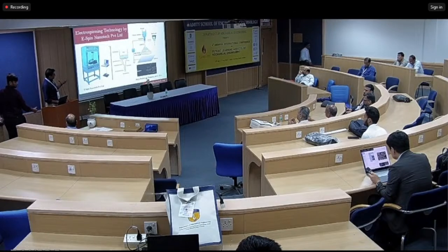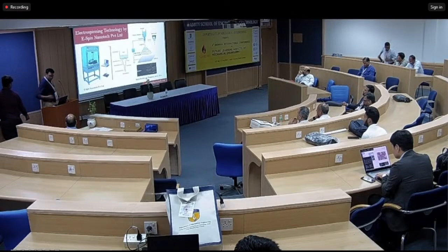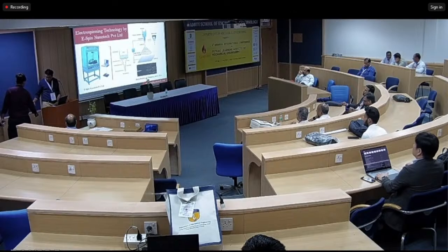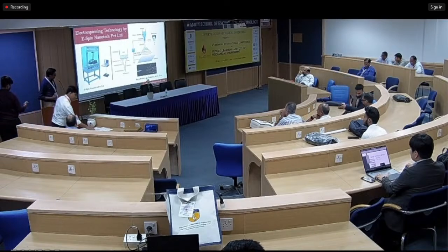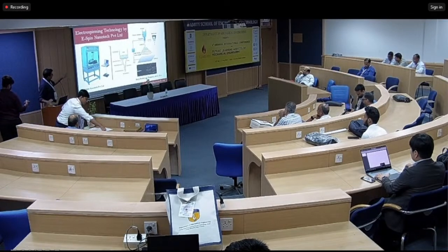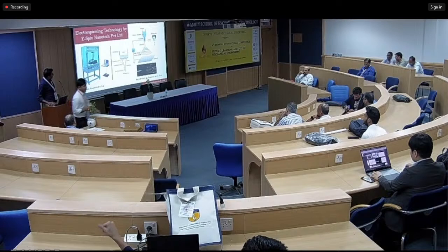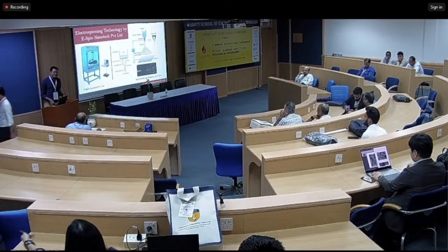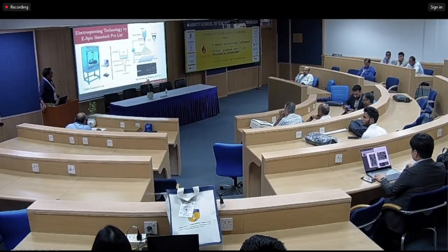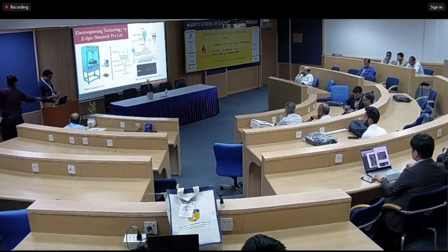So this is a DC power source where you can apply the high voltage, as I said, from 5 kilovolts to 100 kilovolts. You can see this is the geometry of the cone. The moment you apply the high voltage towards the positive electrode, this syringe is filled with the solution. The solution can be a polymeric material which is a linear chain, made with solvents, and the solvent will be a highly polarized solvent where you can add a polymer at a certain concentration. That concentration will help